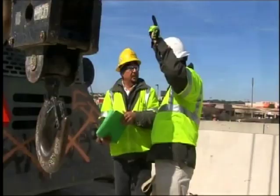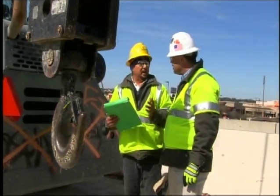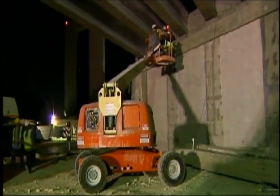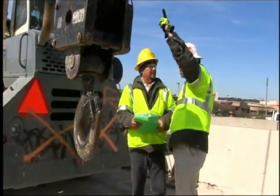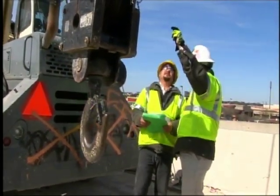If no anchor point is available, it is up to the on-site job supervisor to determine the best point to tie off. Tie off to an adjacent structure is never allowed due to the possibility of being pulled out when the lift is moved. Your employer and the manufacturer of the lift in use will provide more precise fall protection rules and guidelines.